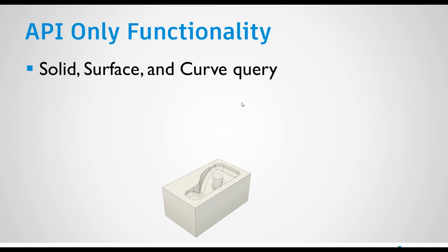I can get their shape, interrogate them for tangents and curvatures, and then find out which faces connect to those edges. So I can really get the complete information from the model geometrically and topologically. So it's a boundary representation model of the solid surface.